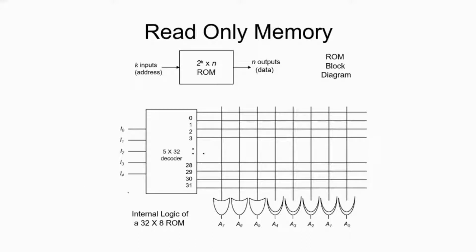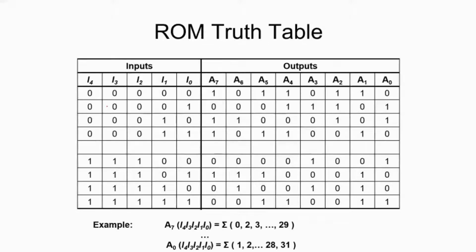So how it is programmed: it has to be programmed, what we call burning or programming at the time of manufacturing, which we cannot practically do here. So what we will try to understand is how we can express that the programming has been done. We'll see the programming table. A ROM truth table has been given here. It can be given in this form, I can provide you like this. See that this is nothing but a sum of min terms.